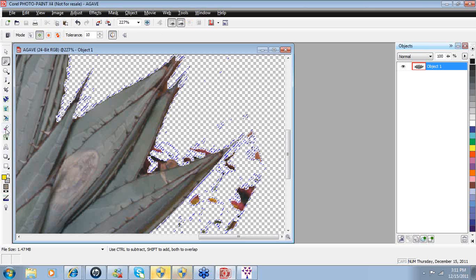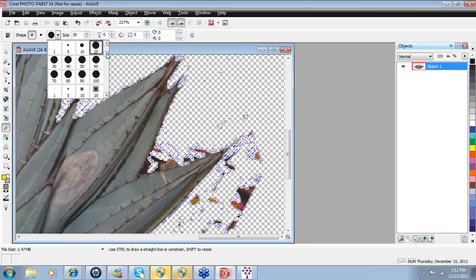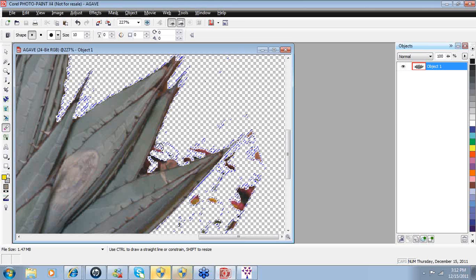Another function that you can use or make use of is the eraser tool. The eraser tool allows for you to change the brush shape and the size for that eraser function. I would suggest when you are erasing, use the solid shapes. Do not use these gray translucent edge shapes. The reason being is because they're going to leave some of that pixel litter on your screen.